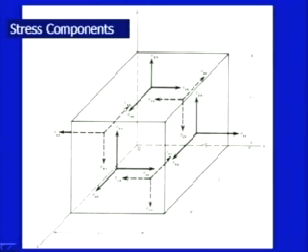As we have seen here, these are my axial stress components in the x, y, and z directions. So there are a total of 3, 3, 3, 3 and these are all six faces, and on each individual face there are three individual components in the respective directions. So there are a total of 18 stress components to describe the stress at a point.